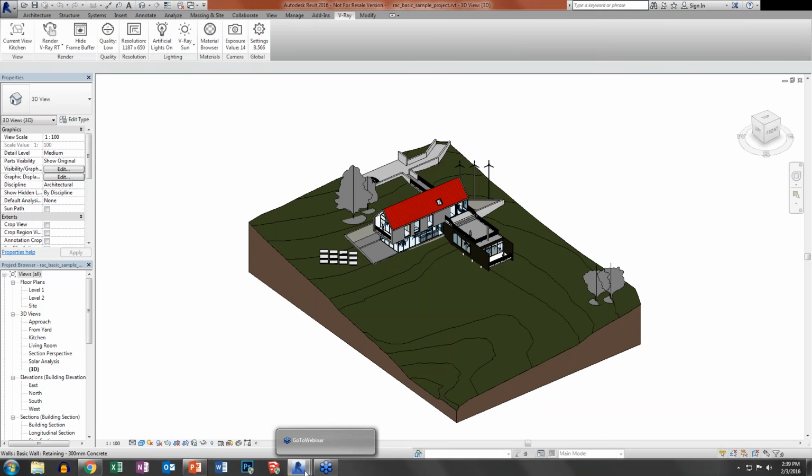We've done some fun things with the ability to support SS2 shaders. Most of the shaders that are built into Max you'll be able to bring in and are supported one-to-one in Revit. And you can do individual material overrides as well as larger material overrides. So for instance, a toon-based material. We've created a toon-based shader in Max. We've brought it over. And the same thing applies actually with Rhino or SketchUp. In the latest versions of those, you can actually create materials there, save them as VR mats, bring them in Revit, and use them in Revit as your materials as well.